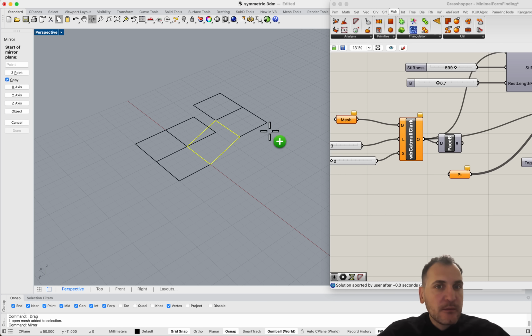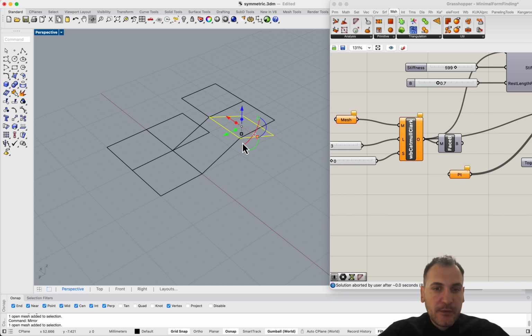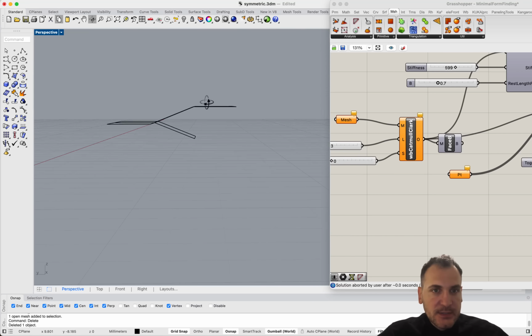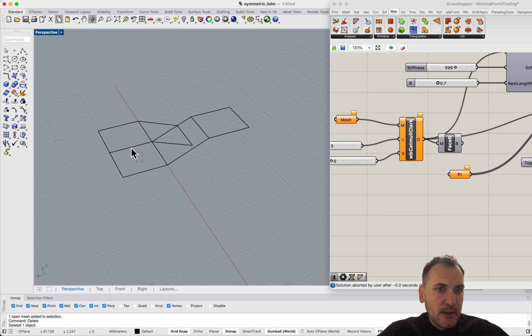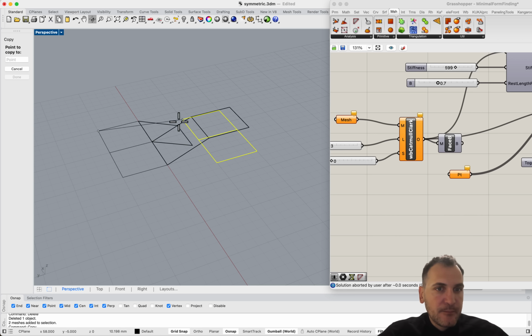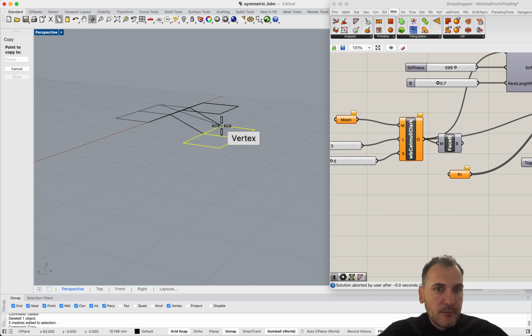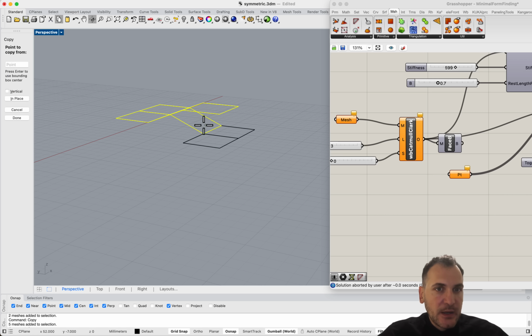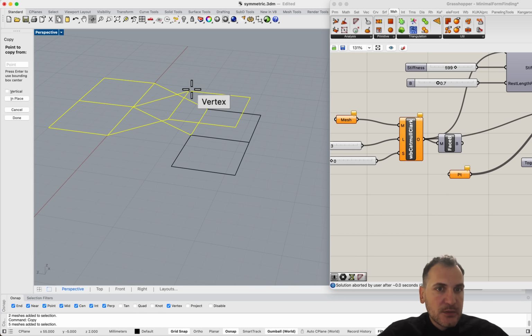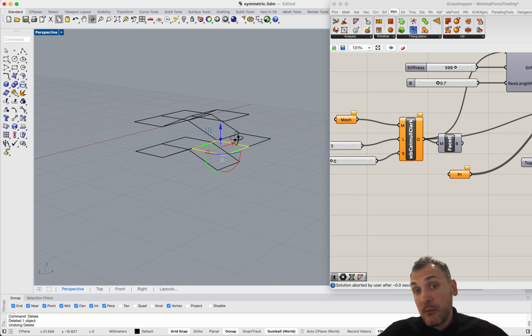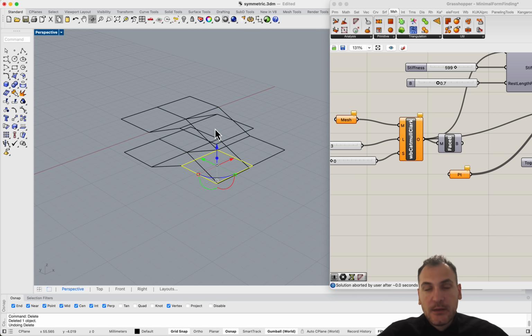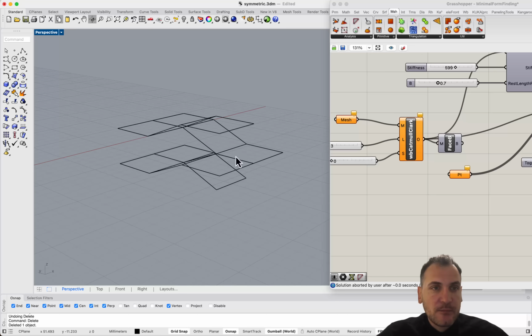So I'm going to build, call this mirror, and move this here. So that's kind of the staircase, right? Staircasing function. And then let's keep building these, and I'll just make a copy of this vertically. So this will go down here. I have double faces here, which will be a problem. So you want to maintain single faces on the construction.